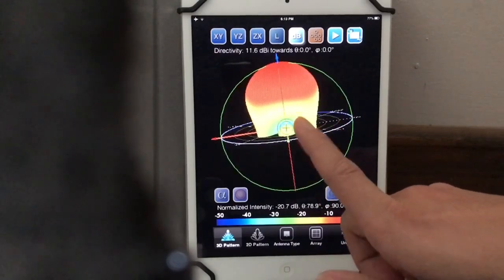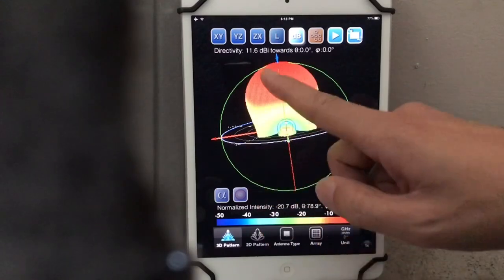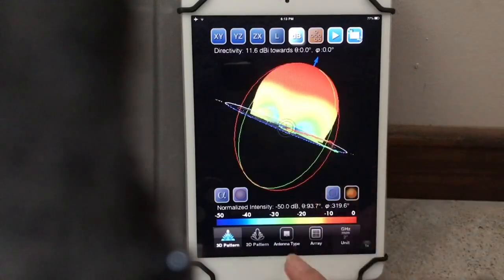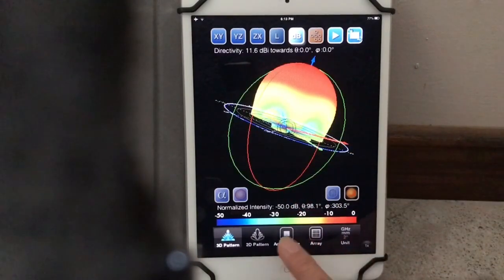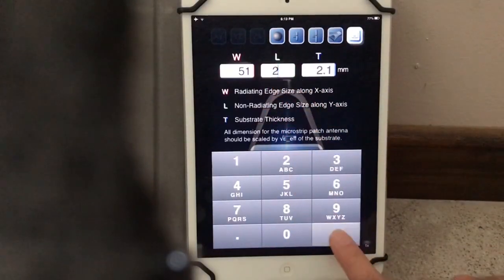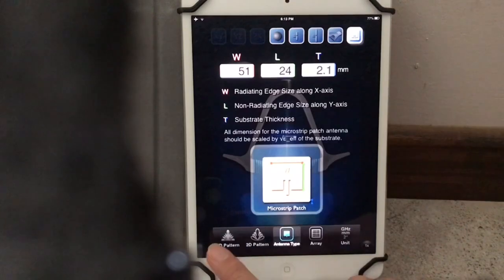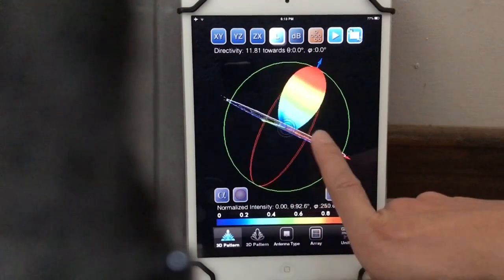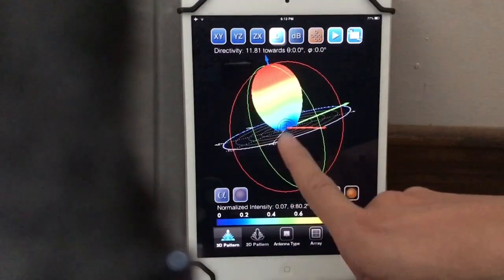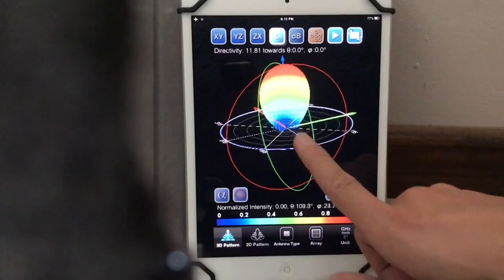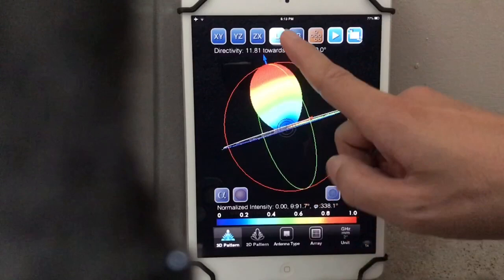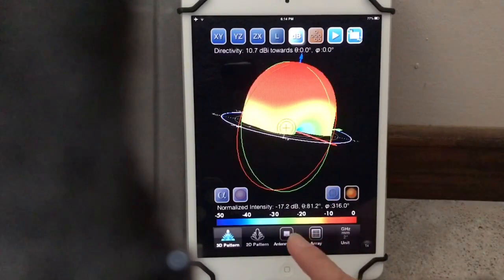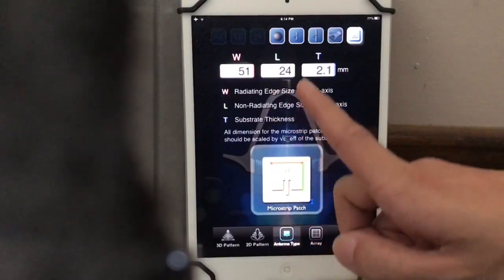If you are flying long range, you will go for higher gain and narrow beam. But for all round flying, I think I'm going to set it to a wide beam. So I'll go with 24. Yep. That's pretty much the kind of beam that you get with 4 turns or 5 turns helical, and gain is about 10.7, which is pretty good.